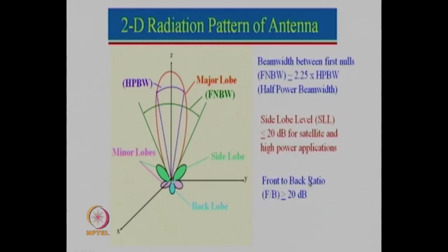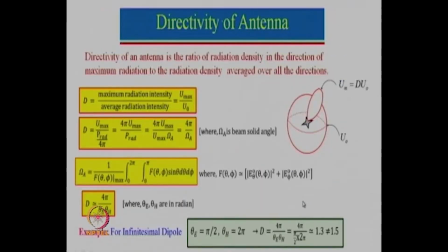Front to back ratio generally preferred is 20 dB, but 15 dB may be acceptable in some cases, but many a time the requirement could be 30 dB, 40 dB front to back ratio.